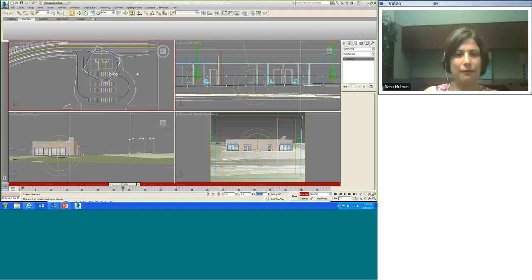So that is the purpose. That's what we want. Now the second keyframe has been set at 33. Now let's move the slider bar and drag it over to the 66th frame so that we will set the 3rd keyframe, and then rotate the dummy object, which will in turn rotate the camera, by minus 240. So right here, and press enter.